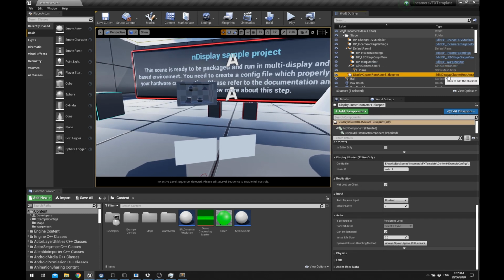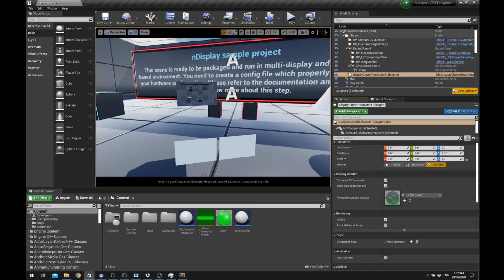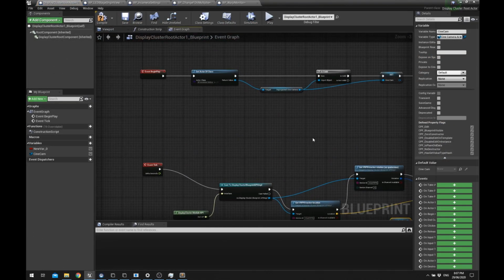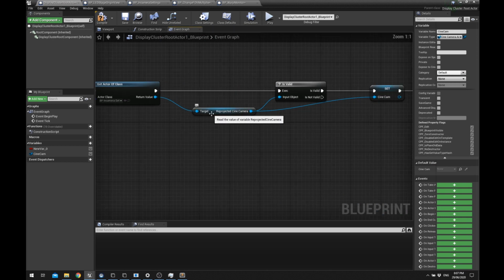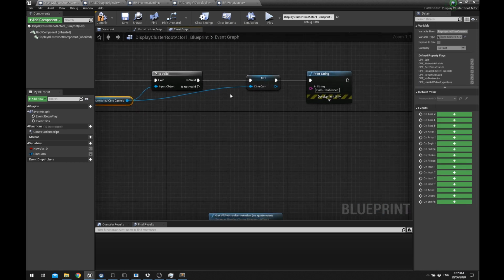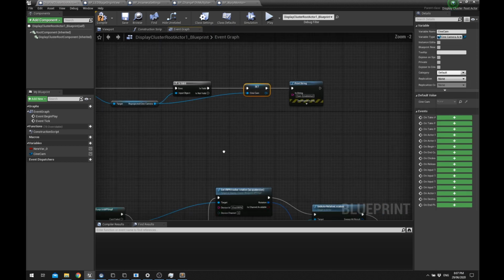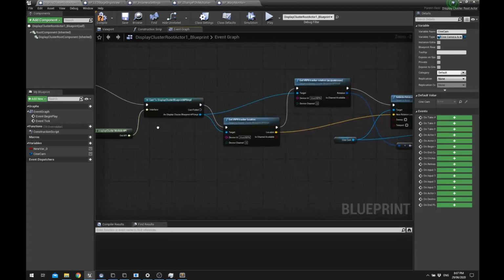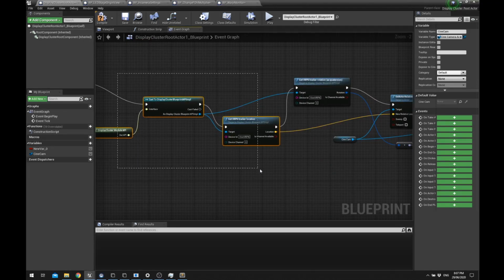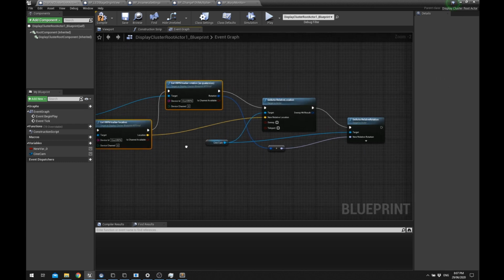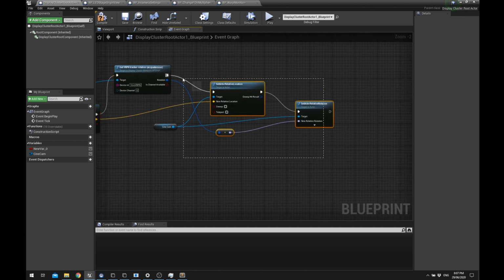So just back in the display cluster, it is being specified to grab the camera that the in-camera settings knows about and put it in a variable so I can reuse it. Then, similar to Ben Kid, we're just grabbing the data from the VRPN tracker location and rotation, and we're making that camera stick to it. We're just making it follow along.